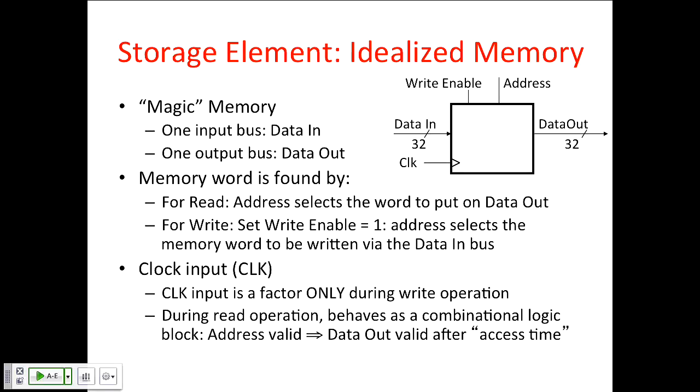So the notion here is that you can imagine the memory being a whole set of registers, and the address you send in tells it which register you want to access, and then at the clock edge, you're going to update that register with the new value you've written. Okay, and for now, that's a reasonable model of the whole memory. It's just a whole bunch of registers that, at the clock edge, you've selected one of them to be written with the value you've presented on the data input.